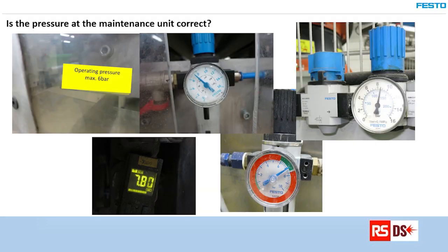Normally, the designing of the machines from the machine builders is for pneumatic 6 bar as pressure. This is not a directive, but in many cases it's a standard. Higher pressure at the machine definitely does not increase the performance of the machine. The cycle time will be the same because the cycle time comes directly from the PLC.